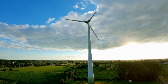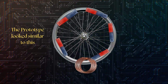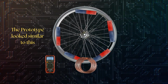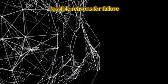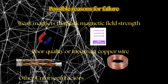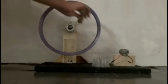I originally wanted to create a generator that uses actual copper wire and magnets to generate voltage. I was able to create a prototype which involved spinning magnets passing by a copper coil. After many tests, this generator was unable to produce a sufficient voltage. Some reasons I think might have caused this could have been a lack of magnet strength, inadequate copper wire, or some other unforeseen factors. Therefore, I chose to create the motor design because of its efficiency and reliability.